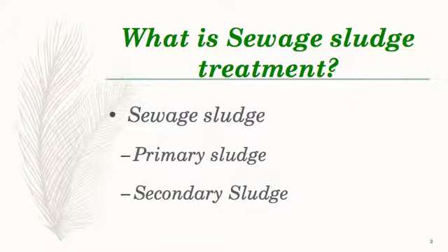So sewage sludge treatment describes the processes which are used to manage and dispose of sewage sludge produced during sewage treatment. Sludge is mostly water with a lesser amount of solid material removed from the liquid sewage. The primary sludge includes all the settleable solids which are removed during the primary treatment in the primary clarifiers. Secondary sludge, separated in the secondary clarifier, includes treated sewage sludge from the secondary treatment bioreactors.